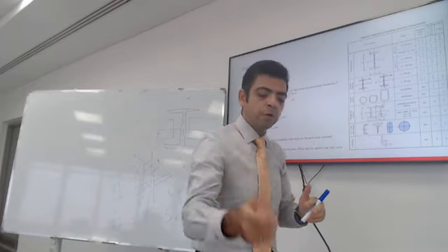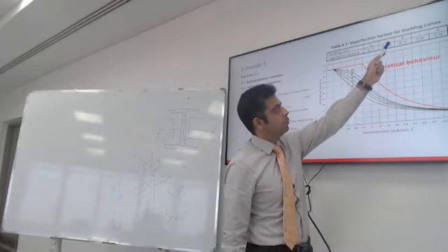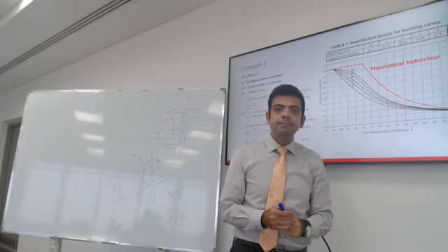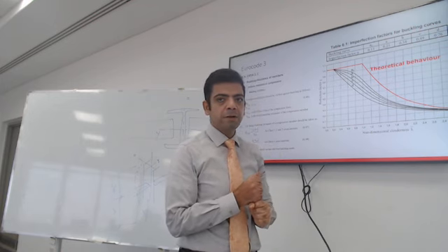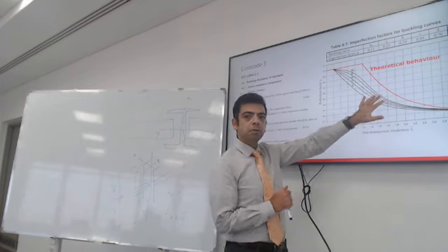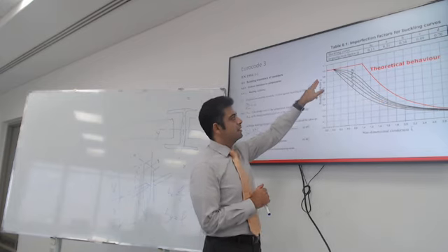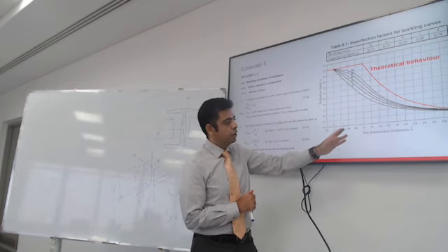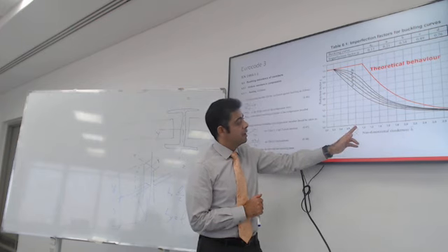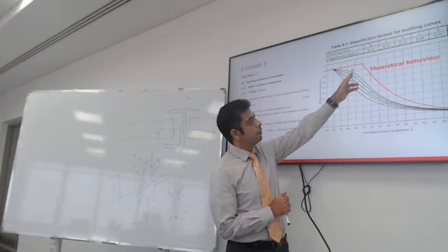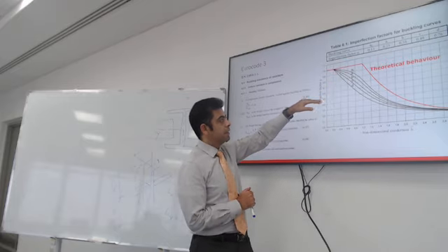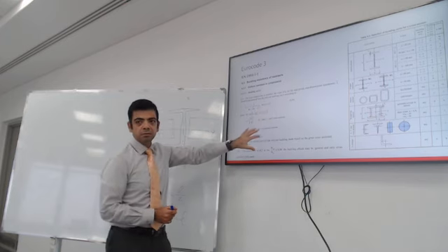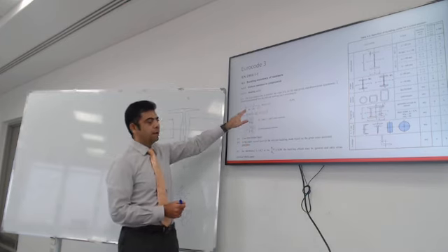Okay. So if you're going to use curve A, you go to the imperfection factor table for the buckling curve and use this number, 0.21. Why do we need the imperfection factor? Because this is how you get the reduction factor. Using the graph of the reduction factor against the non-dimensional slenderness, you hit the buckling curve according to your imperfection factor, and then get the reduction factor. But you can also calculate it from this equation. This equation will tell you what the reduction factor is.